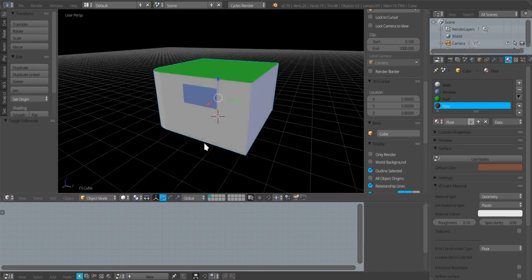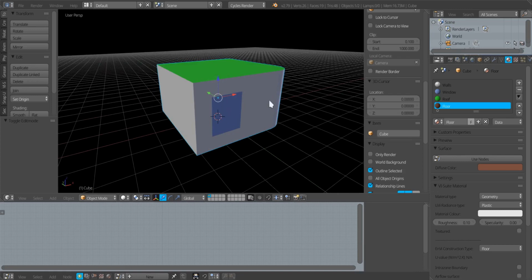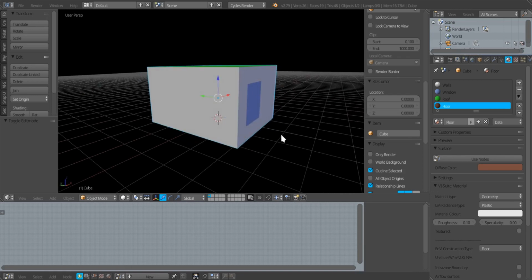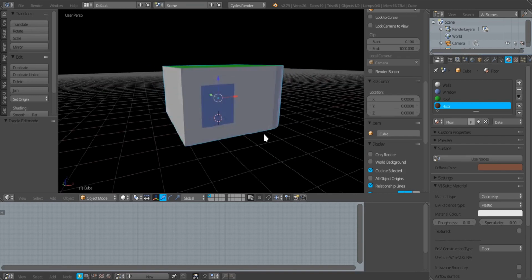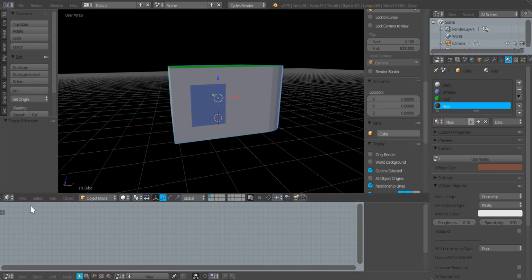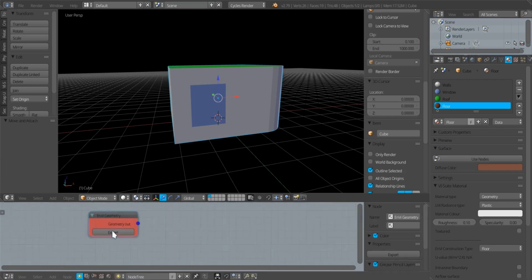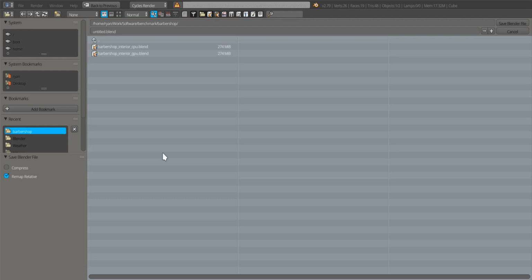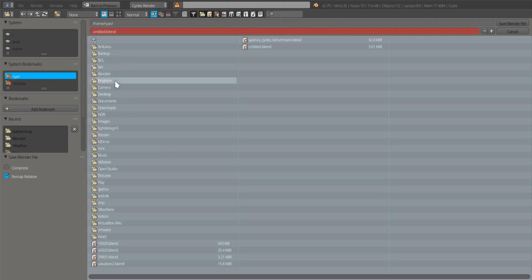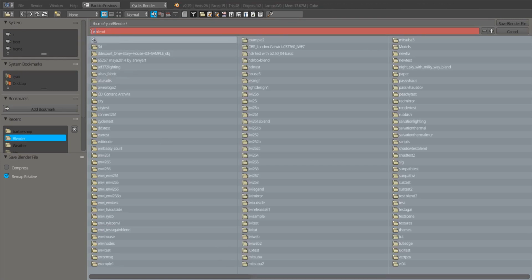But when we export this, the V-Suite will also do a check for us. So let's go and export this Blender geometry into Blender geometry more suitable for an EnergyPlus simulation. I've got my node editor open down here, and I've got my V-Suite VI network node tree group associated here. I now want a new node tree within that window, and now I can add a process node, EnVi geometry. There are no options here. There might become some at one point in the future, but at the moment they're not necessary. So we can just press export, and it's reminding me that I have to save my Blender file. So let me just do that.